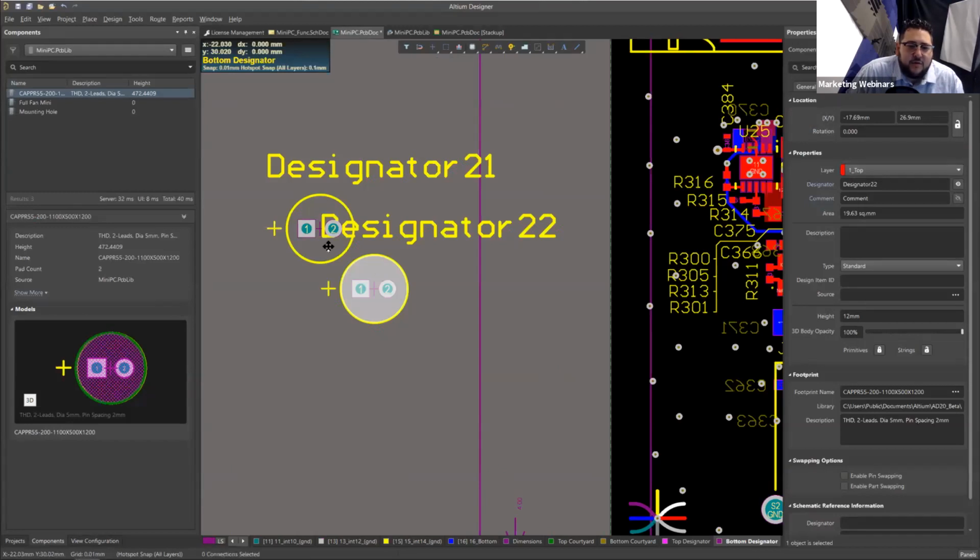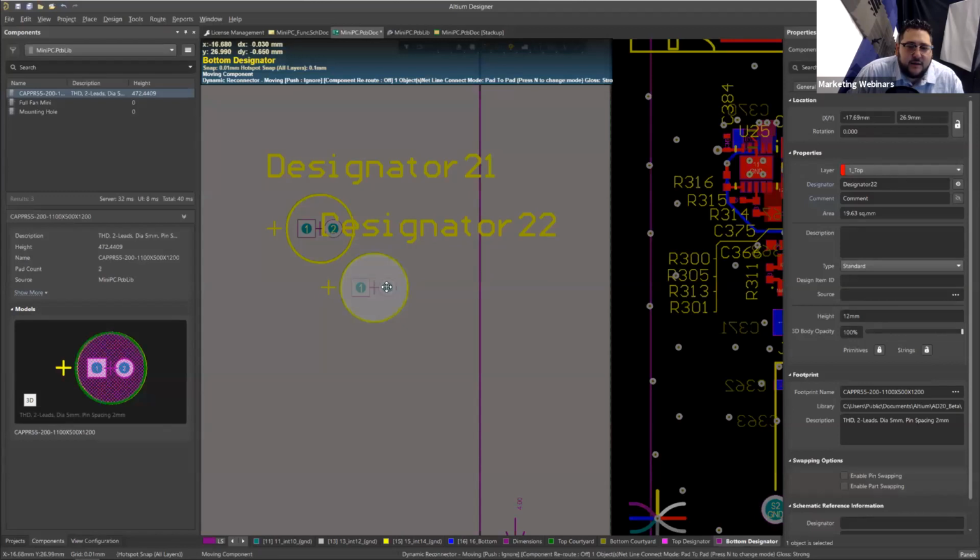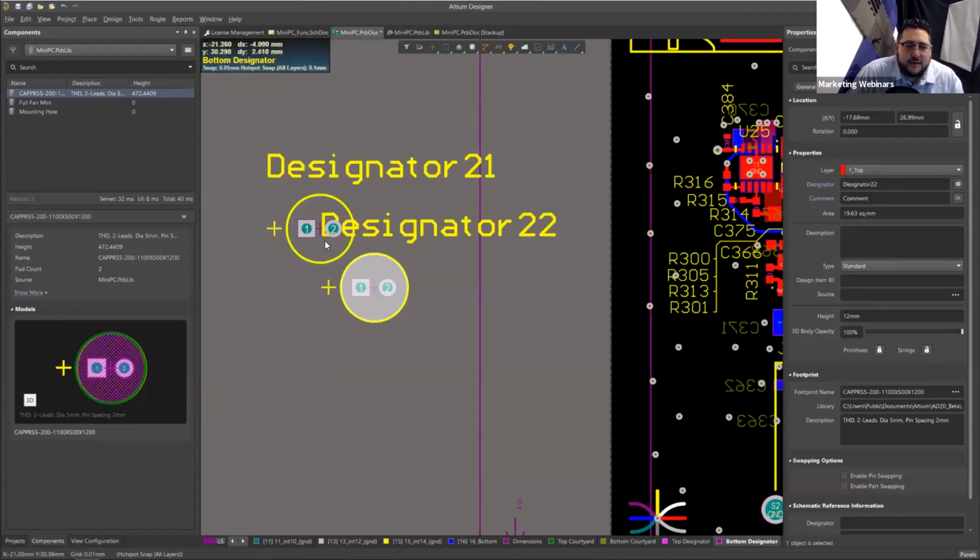You see here when I click on the component itself, now it is selecting them with courtyards, and we would no longer have DRC errors. And you could see how that is perfectly selected. So if you have a component with a very unique shape, you simply define the courtyard perfectly as need be, and you can make sure that you don't have any issues.